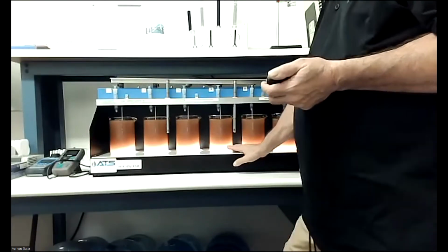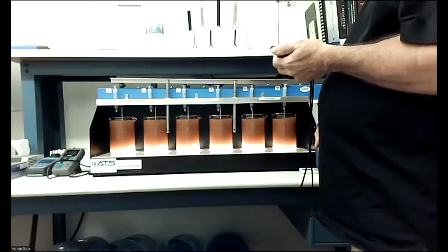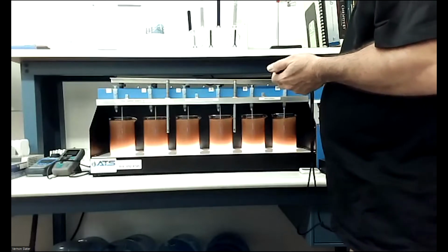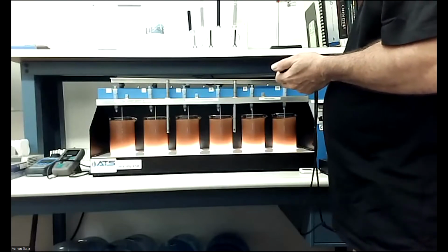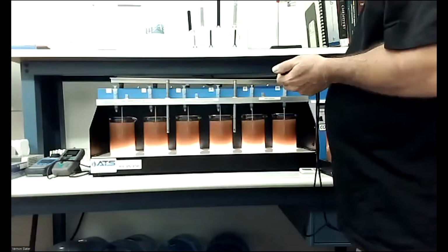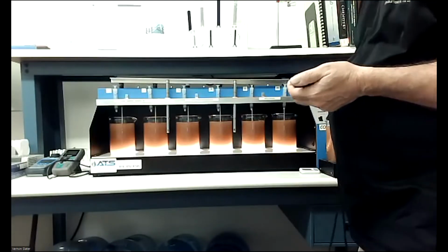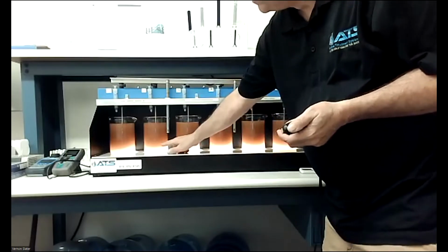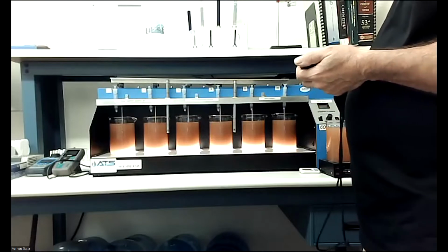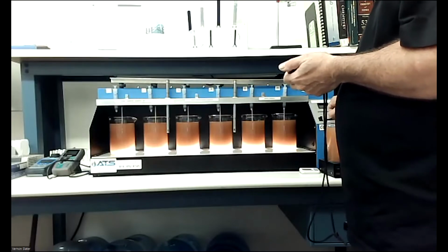And now I know you guys can't see it, but I can already see floc forming in the bottoms of these jars as it's spinning. But it'll become a little bit more evident here as I slow this down and stop mixing. I'm going to go right to a slow mix. And I'm going to go about 30 seconds more. And I'm not sure if you can start seeing this floc. A lot of thick particles forming. All right, and I'm stopping it.